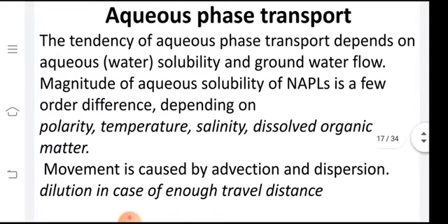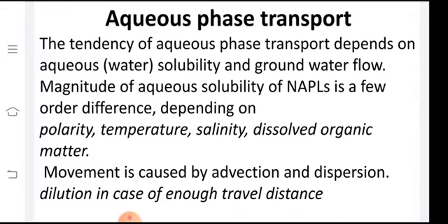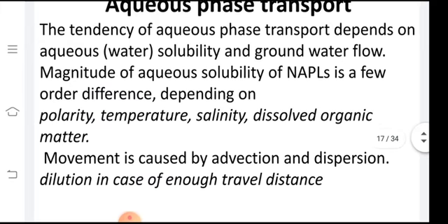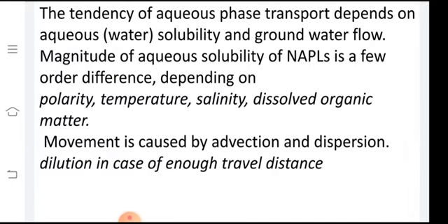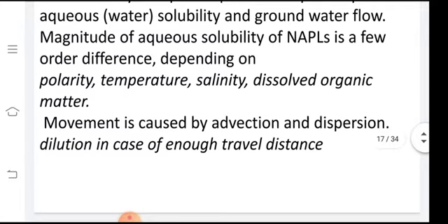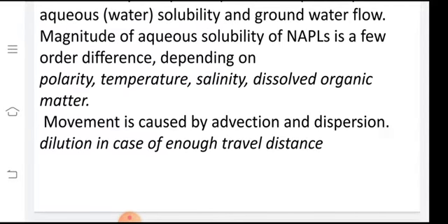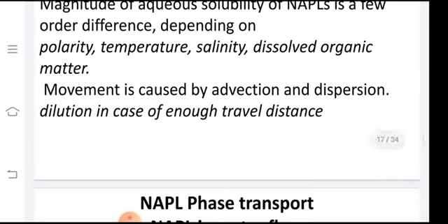These are the basic properties once the NAPL enters the aqueous phase, and it will follow these properties. Temperature will be effective, the salinity of the aqueous phase will be important, how saline it is, and how much dissolved organic matter is already present in the aqueous phase. It is important, because if it is already saturated, it will not have the possibility of accommodating more dissolution from the NAPLs.